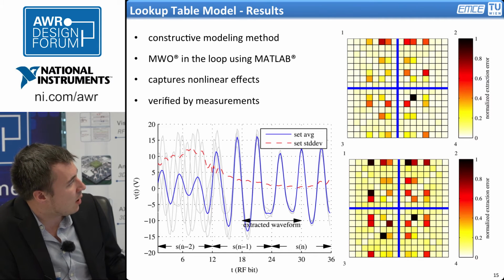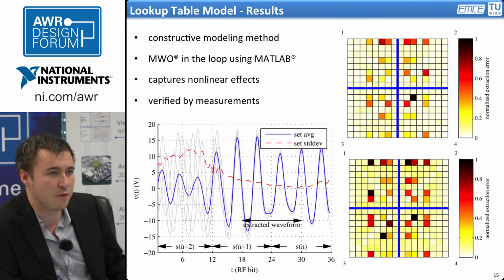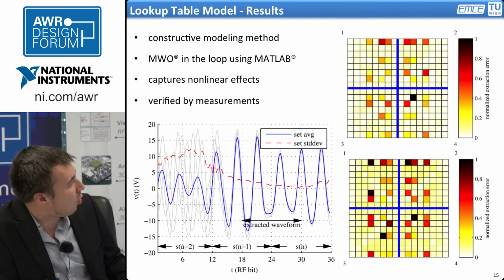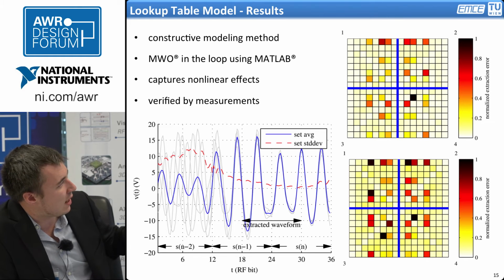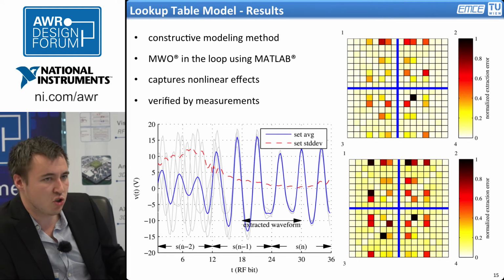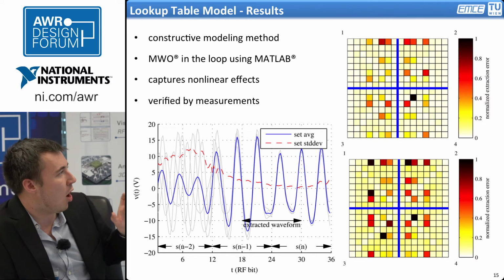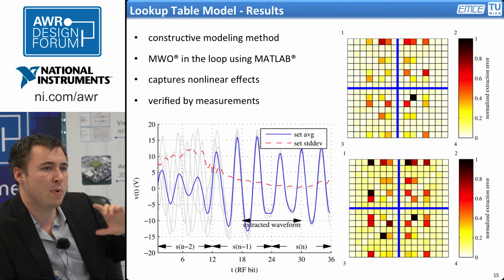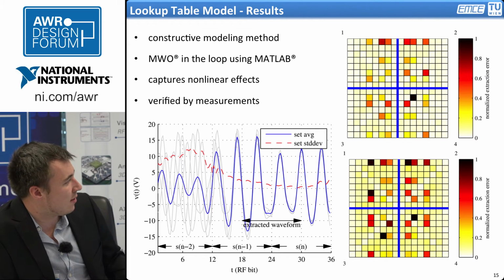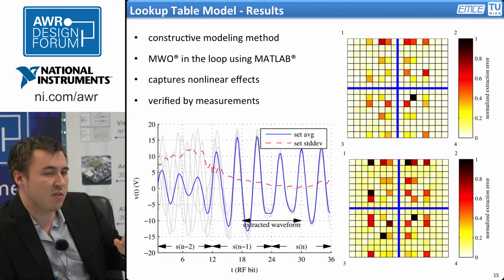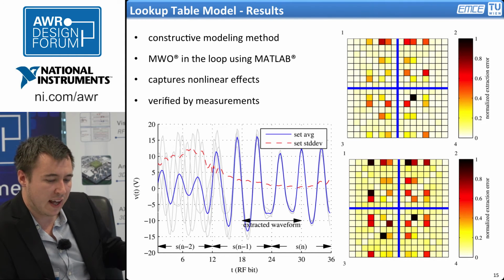And now we end up here with these very colorful charts, where the top one is a measured one and the bottom one is a simulated one, and every pixel in this chart stands for one group of excitation signal, and the color indicates how well they are going to be predicted by the nonlinear circuit simulation for a specific chosen memory length.